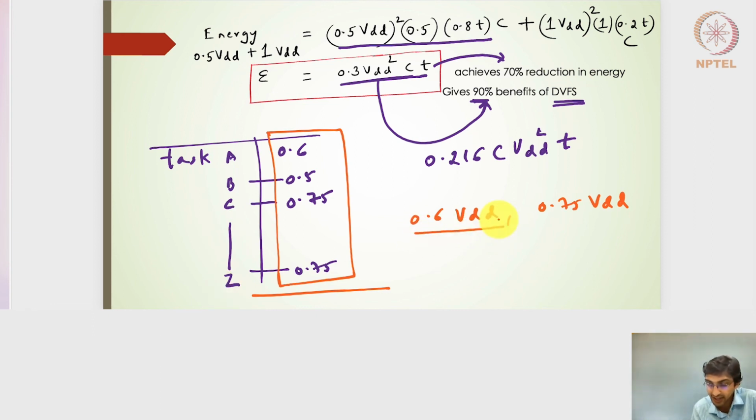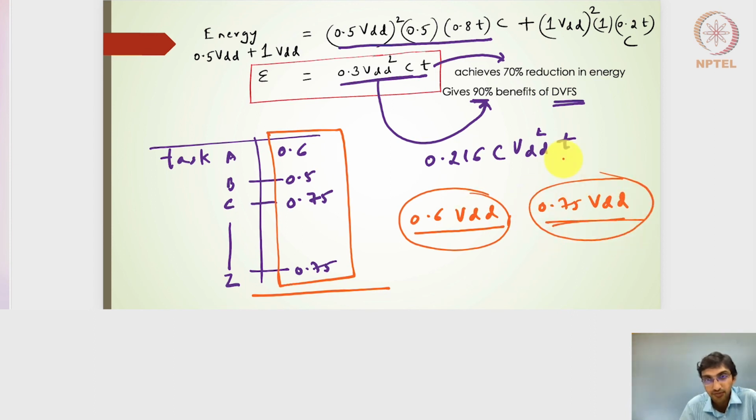So the rail voltage design actually comes from the characteristics of these n tasks, which are going to use the VLSI design we have done on one particular part of the chip. For completing the tasks using that design, we need to calibrate or characterize those tasks and determine what the rate should be. Based on that switching rate information, we should be able to design the optimal rail voltages, right? And then this can be applied to all the tasks. All right, so I hope this is clear.